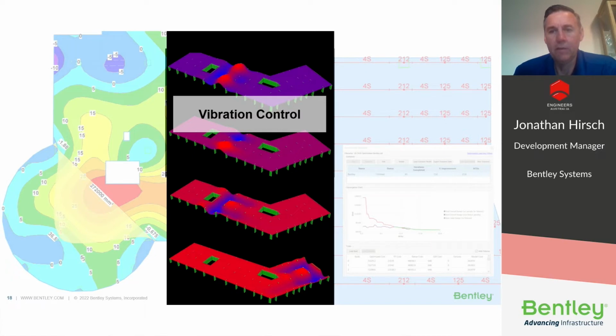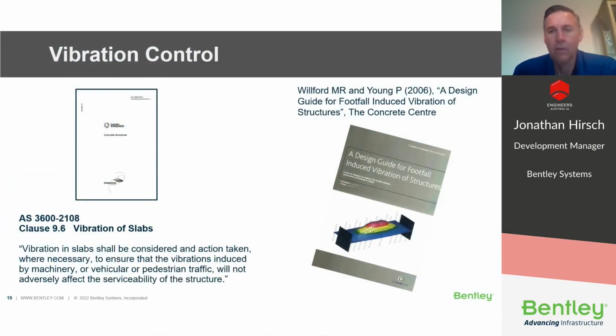I'm now going to discuss the next topic in the presentation, which is vibration control, with an emphasis on footfall-induced vibrations. Vibration considerations have begun to make their way into building codes and standards, and as such, they've increased in importance recently. Vibrations can be induced by machinery, by vehicles, or people, and they can also affect equipment or people. So people walking on a structure can disturb other people that are on the structure, or they can disturb sensitive equipment, such as certain microscopes.